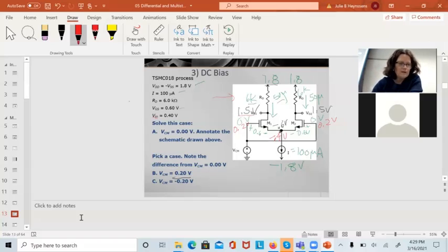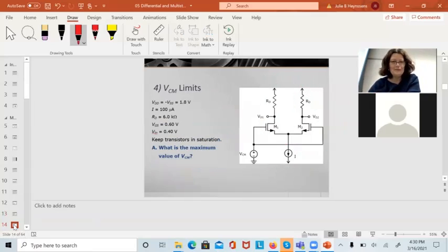Okay, why was that important? We'll get to that. The current will split across the two branches evenly as long as the voltage on the two gates of the transistors is the same. If I put a differential signal across there, that's no longer true. We will get to that today. I took an entire senior level course on this one circuit. It's hard to do this all in one day or in a couple of days as we've done.